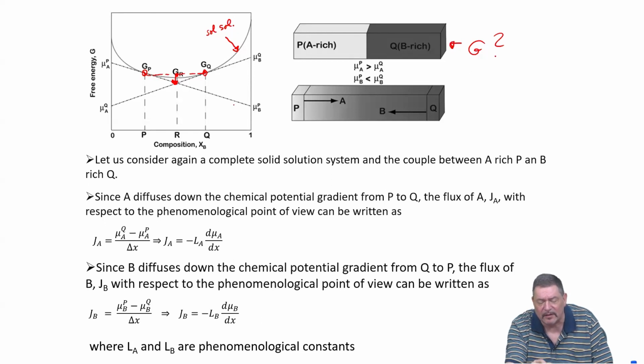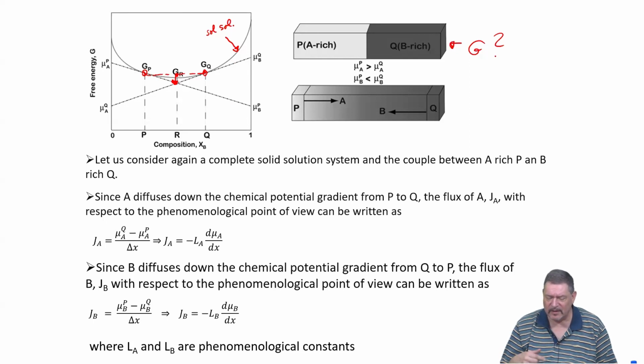So these dashed lines are the chemical potentials for the given situation. And basically what we can describe then is a diffusive flux also being driven by the gradient in the chemical potential. In this case, the chemical potential gradient and the concentration gradient are pointing in the same direction.